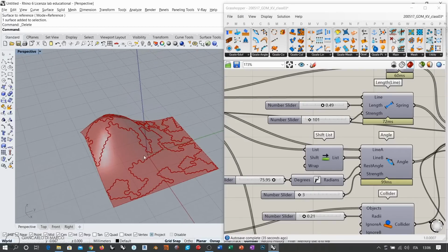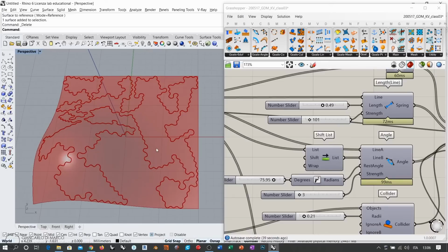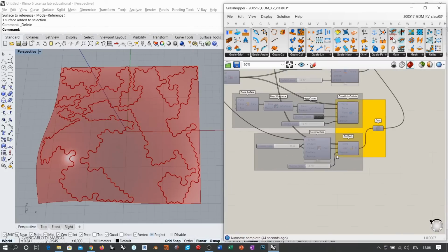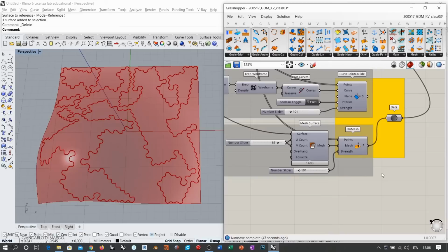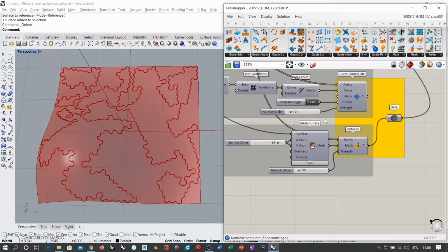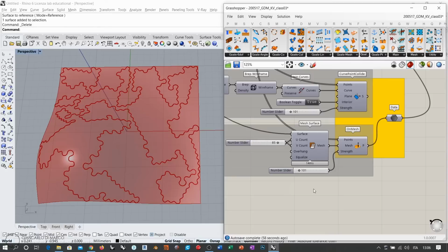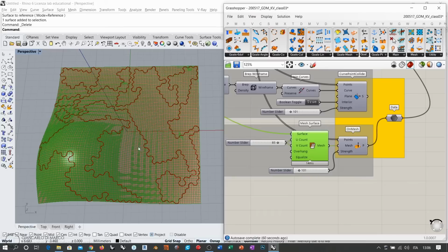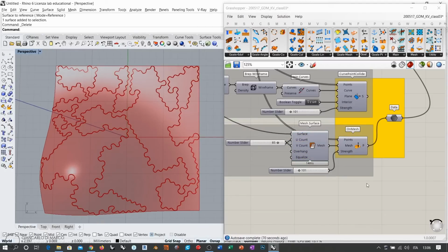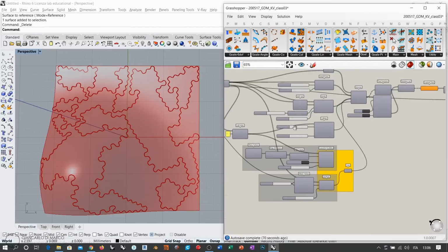So you can apply this technique for designing on every surface that you might want to use. The only thing is that as this on mesh works exactly with a mesh, the easiest way to create a controlled mesh in Grasshopper is to use the mesh surface. There is also a mesh brep, but the mesh brep normally generates an irregular topology, while in this case you have this perfectly controlled topology made up of just quads. So you see a totally different aesthetics for the same script.